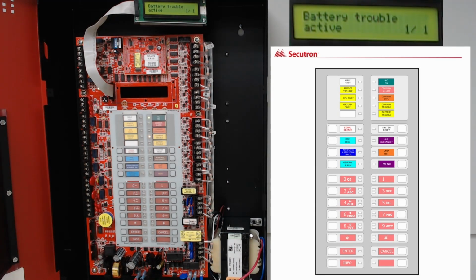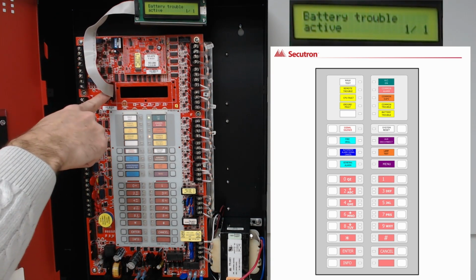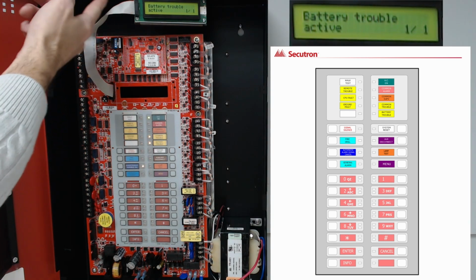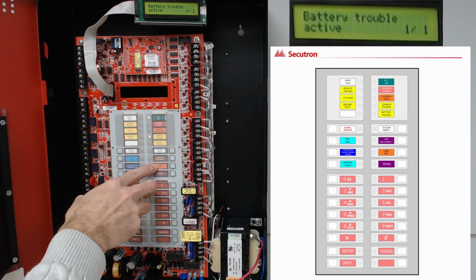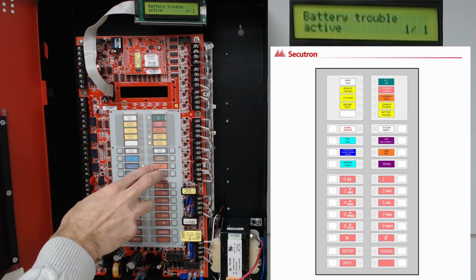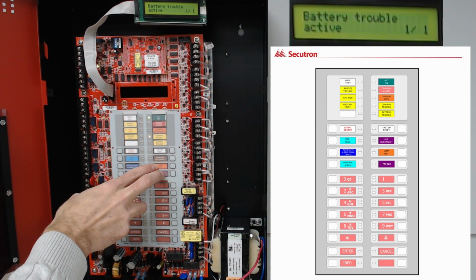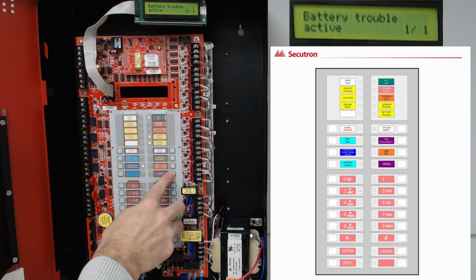Hello, today we're going to be programming the MR2312 LED series fire alarm panel utilizing the CFG 300 programming tool. I've already plugged in the programming tool and mounted it to the top of the back box. In order to enter the menu for a two-stage system, you'll have to select the lamp test and the alarm, supervisory trouble, building audible silence buttons together simultaneously. With this being a single stage system, I simply just have to hit the menu button.